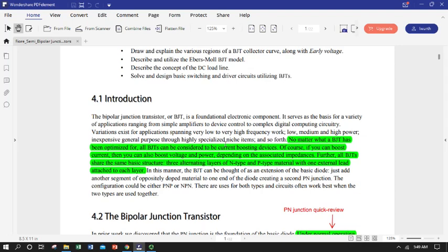We're going to apply current in a small signal to one lead of this device, and in so doing control current flowing across the main body of the device. So a small signal in what we'll term the base of the device is going to control a large signal from the emitter to collector, the main pipeline. So you can think of a bipolar junction transistor as a valve.